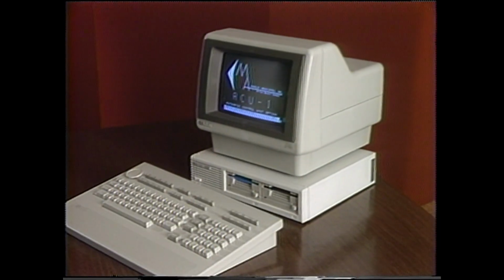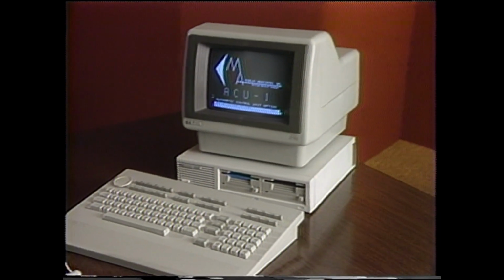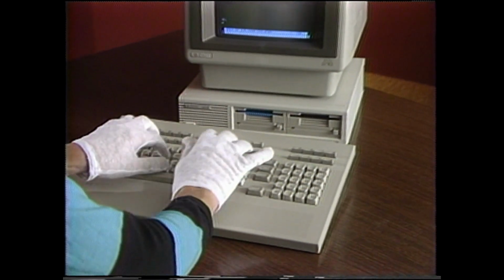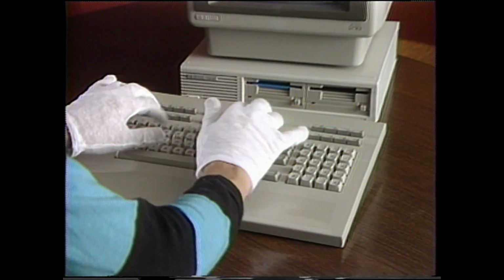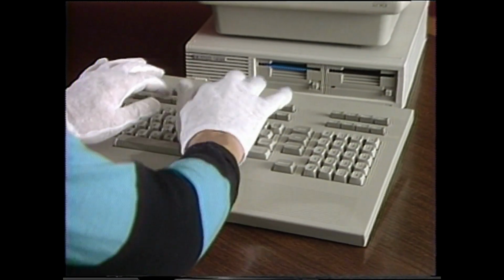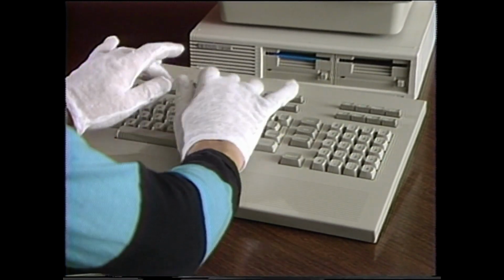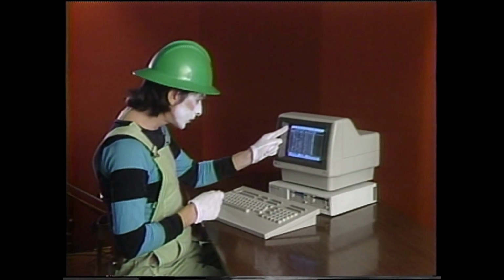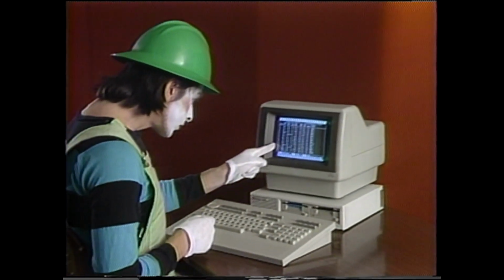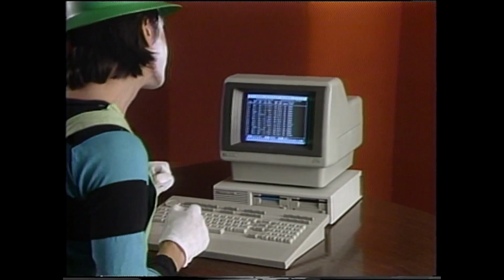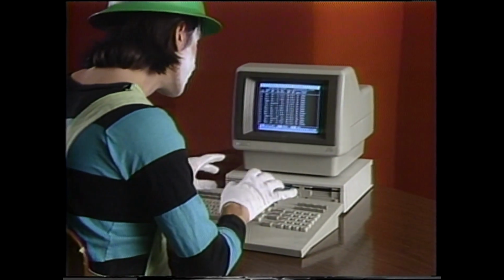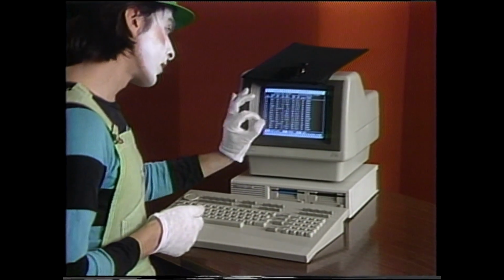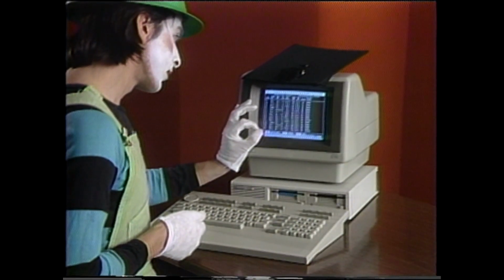For the ultimate in system control, you can have the Moseley Automatic Control Unit, the ACU-1. Your custom program may be entered in BASIC or Moseley Clear language, a user-friendly version of BASIC. The ACU-1 can adjust, reset, and change over equipment based on telemetry values, changes in state, time, and operator initiation. The automatic control unit can be set up to mimic an expert operator, making immediate command decisions based on events.